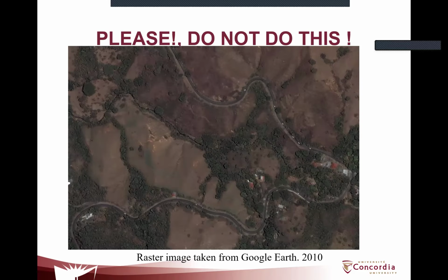You can see here, this is a satellite image, and you can see the use of compound curves back and forth because they're going all the way down into that creek. But these really drop speed, and these really reduce mobility and increase travel time.